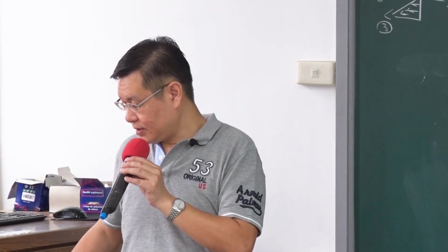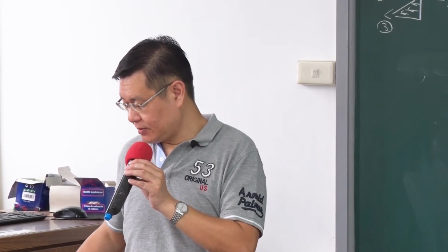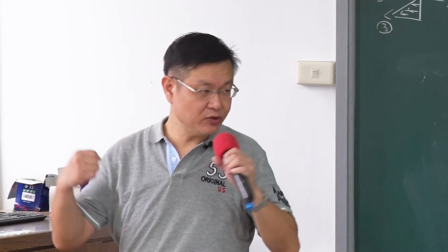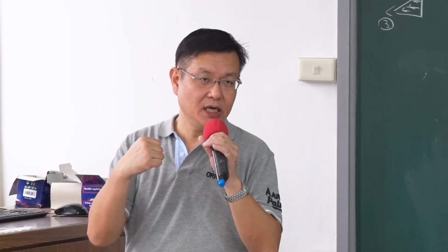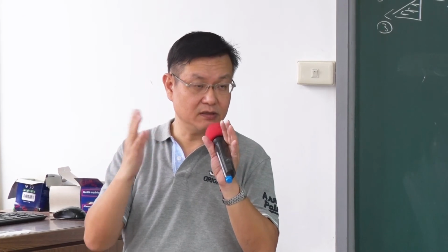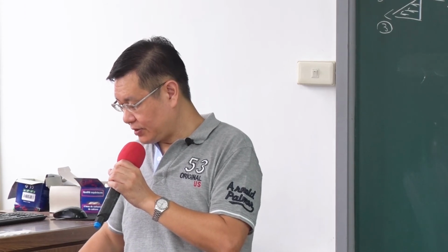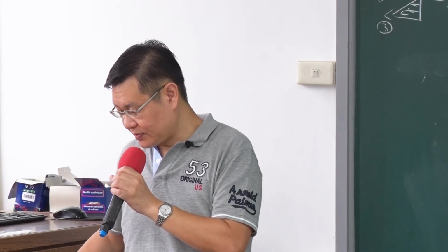Okay, so when you are doing this kind of calculation, you think of when you squeeze the film, the piezoresistivity will be increased. Actually, the sign is negative for n-type polysilicon, which is -15, and p-type is positive. The sign is positive.